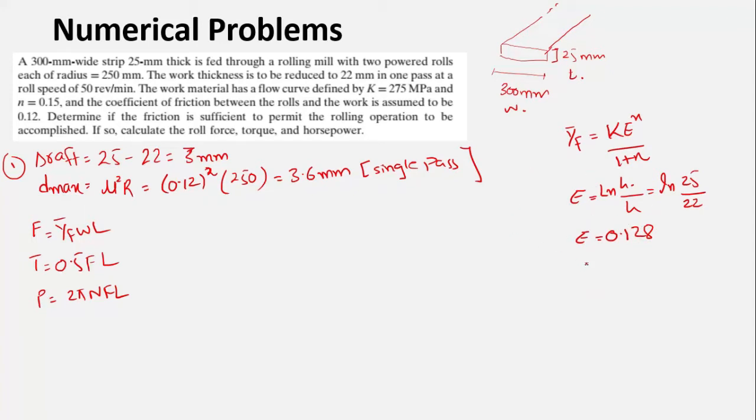We will have Yf equals 275 as a strength coefficient into 0.128 exponent 0.15 as a strain hardening exponent divided by 1 plus 0.15.